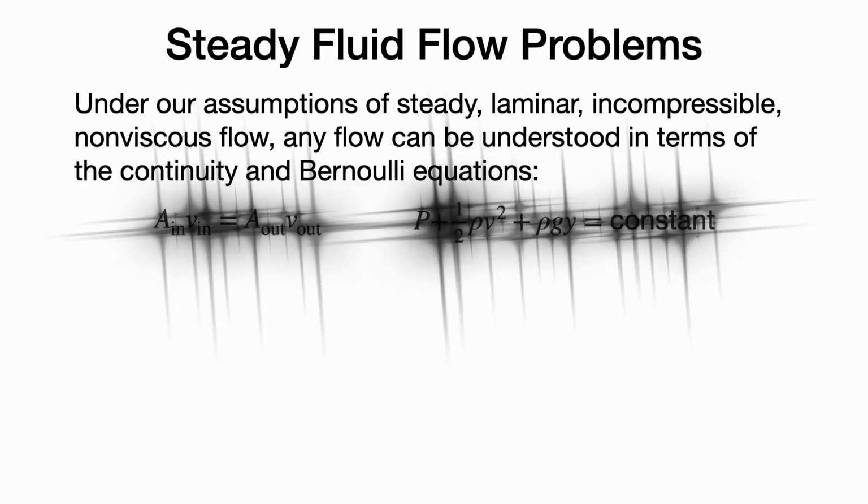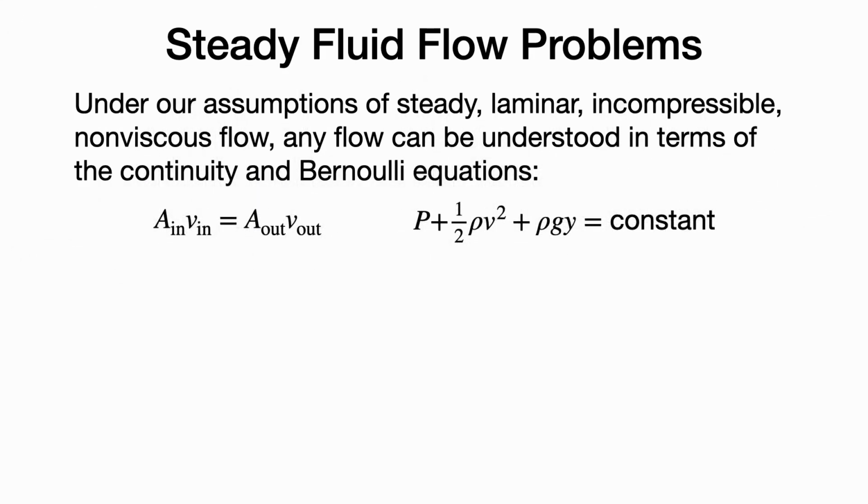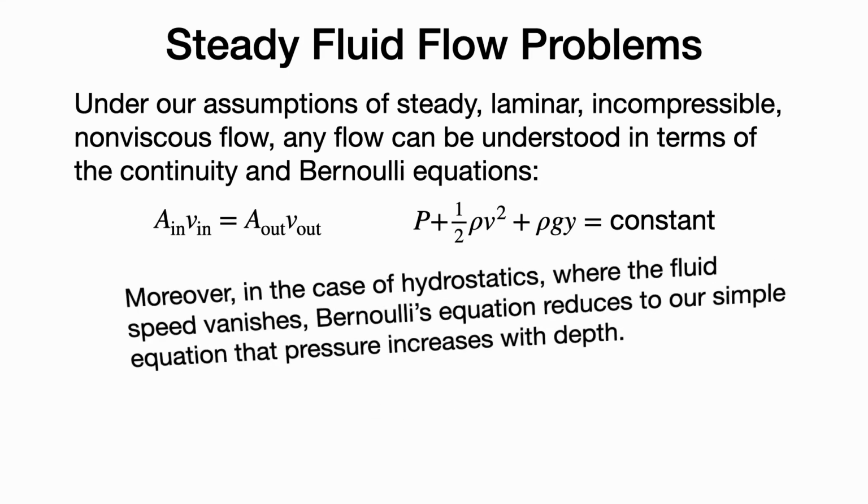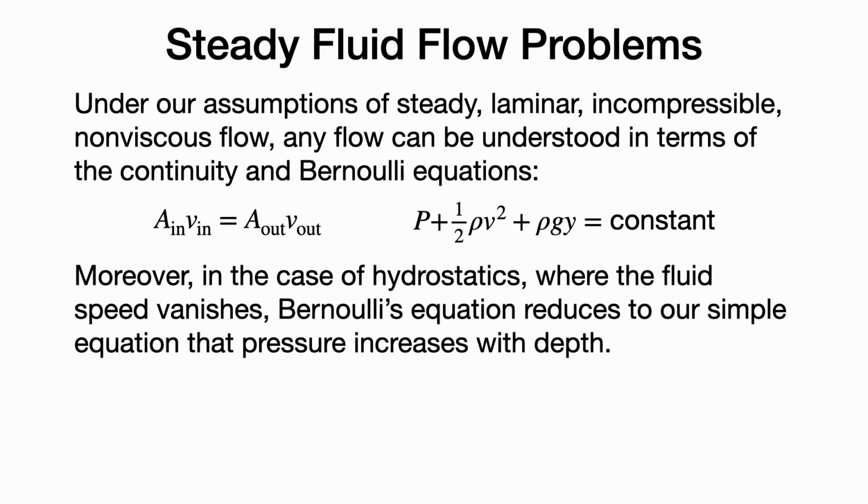Under our assumptions of steady, laminar, incompressible, non-viscous flow, any flow can be understood in terms of the continuity and Bernoulli equation. Moreover, in the case of hydrostatics, where the fluid speed vanishes, Bernoulli's equation reduces to our simple equation for pressure.